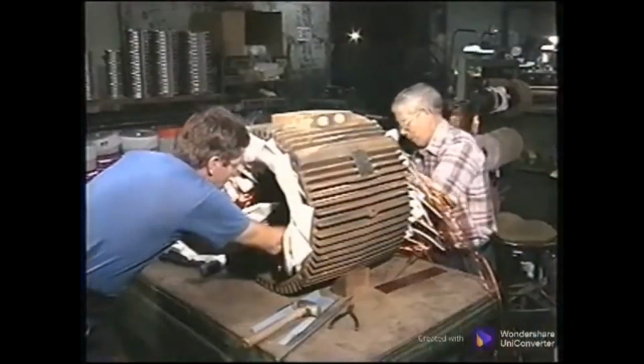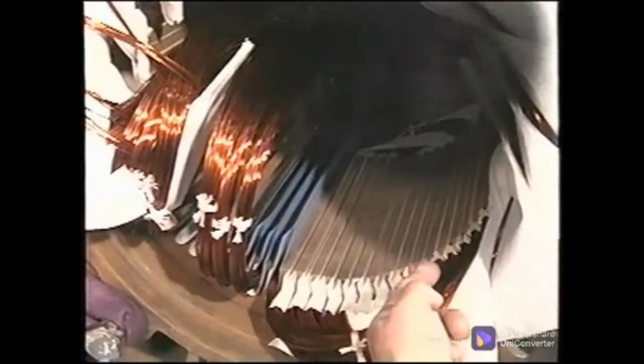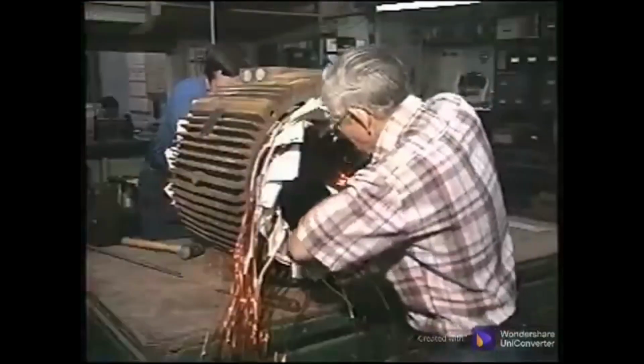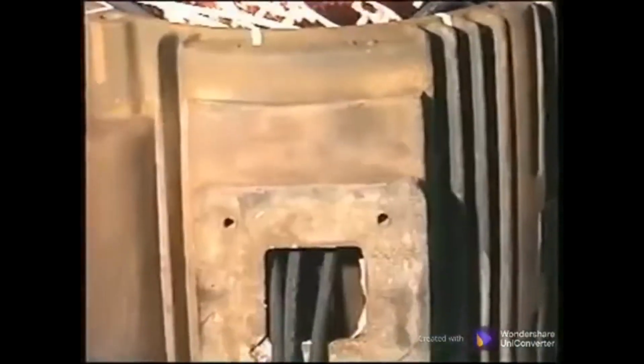They are then pressed into the slots in the core, called stator slots, with heat-resistant paper as additional insulation from the core. Notice how one side of the coil is pressed into the slot and the other side is then pressed into a slot along with another coil. The two coils are electrically insulated from each other with insulating paper. When all the coils are in place, the ends of the coils are connected to form the A, B, and C phase line leads for the motor.